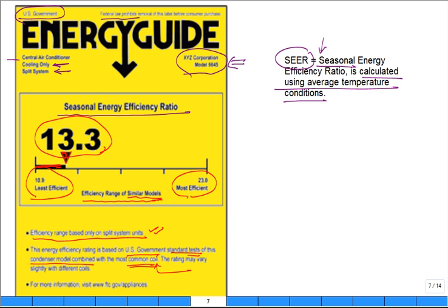Then you also have the fan and the coils. So those are the things that I showed a picture of a couple lectures ago, how they've gotten bigger and bigger over the years, because with larger areas you can have a smaller delta T to reject that heat, and it's more efficient. So the engineers have been trying to improve the efficiency over the last few years.